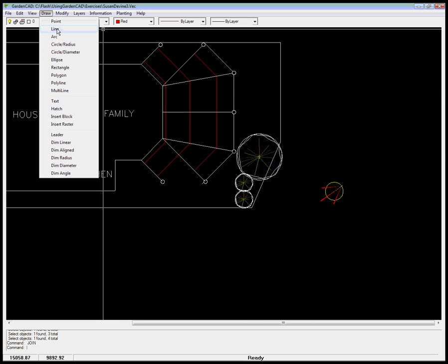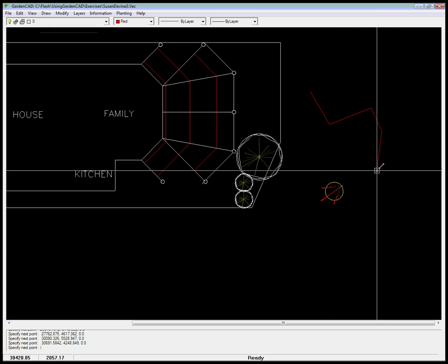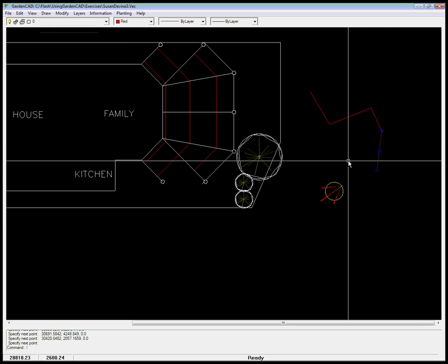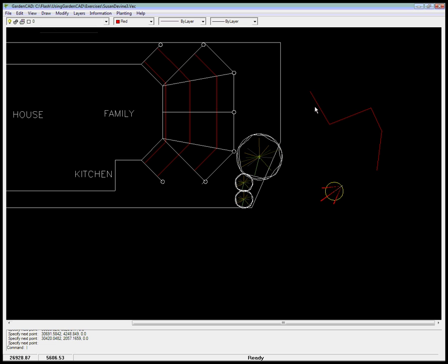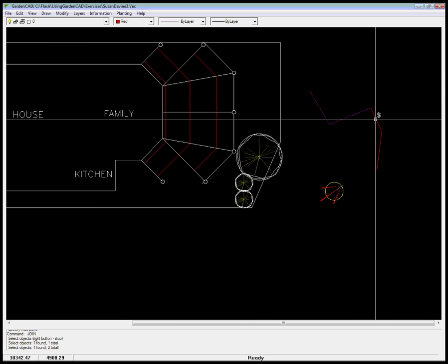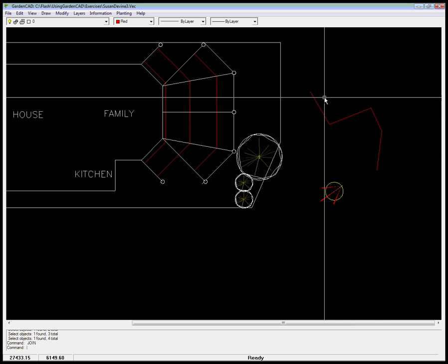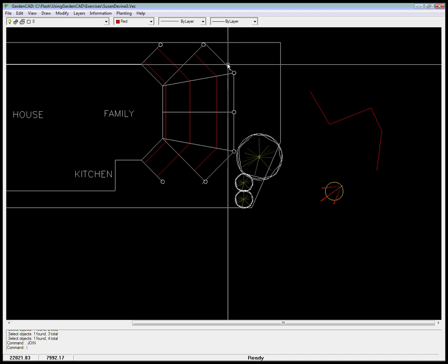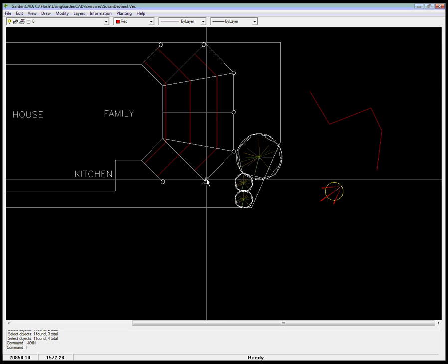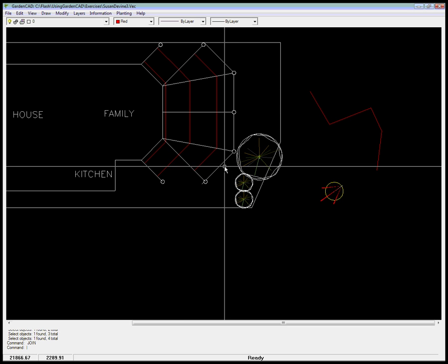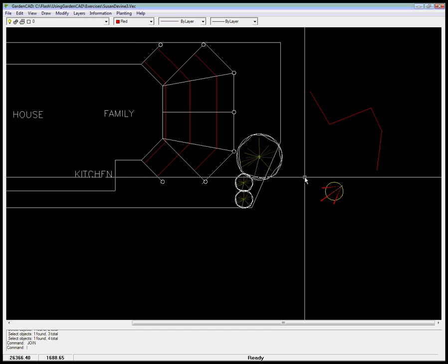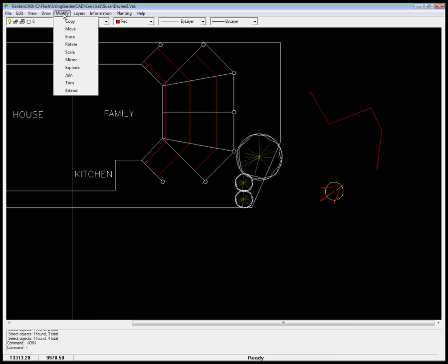Let me just, for my interest, draw a series of lines out here. When I click on an individual line, it's a single line. When I use the modify and join, select that, that, that, that, and right click, and then click on them, they're all one object. So the command is working correctly there. There is some problem with my drawing in here. It is possible that that fails because of the mirroring that occurred in that zone. So there are other ways to overcome that. You could just simply draw over the top of those lines. But I digress. We're looking at these modify commands.